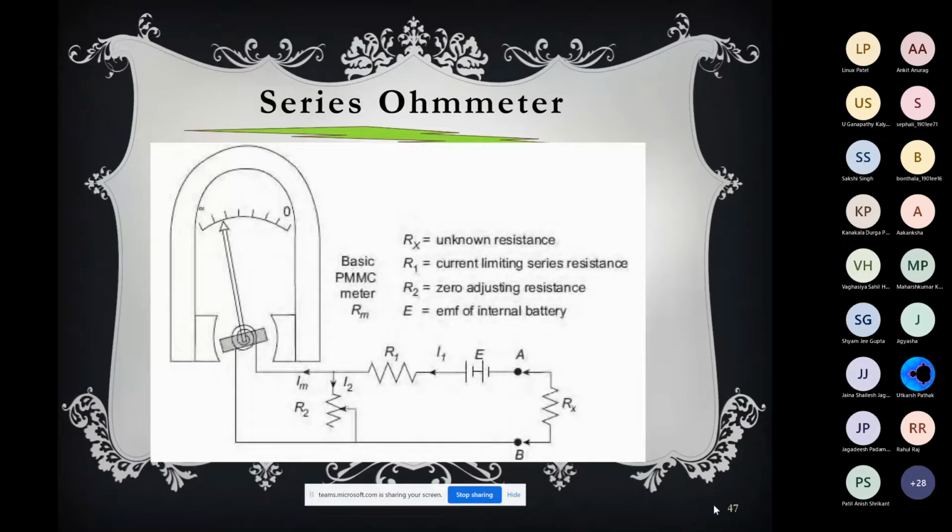Now, another thing I used to emphasize, which is not inside the slide and which is not written in any book: whenever you do some experiment, and I ask what the resistance is, you generally directly, without taking out the resistance from the circuit or without disconnecting and isolating the resistance from the circuit, just put the two probes of your meter on the resistance and it gives some absurd value. Why does it give some absurd value? Suppose you expect your resistance to be say 10 kilo ohm, it might give 450 ohm or many other absurd values.